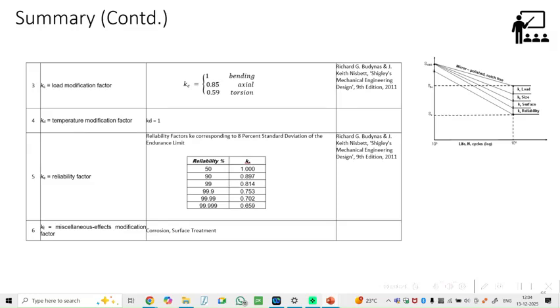If analysis shows that 1.2 mm is enough, but you have a 2 mm or 3 mm sheet, and in the skin pocket it needs only 1.2, you have to reduce it, 2 means 0.8 mm to be removed. Then you have to do the chemical milling. If you do chemical milling, again it will affect the life. That has to be evaluated. I have a nice qualitative picture down the line.